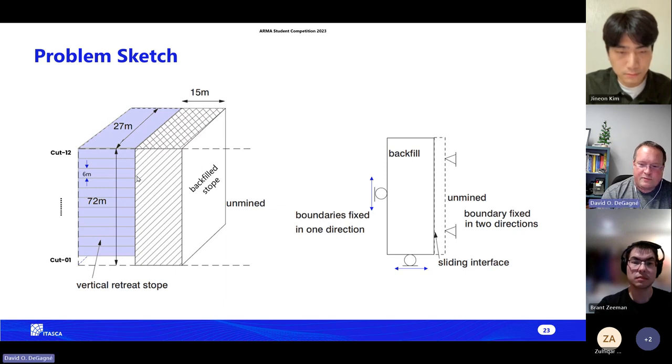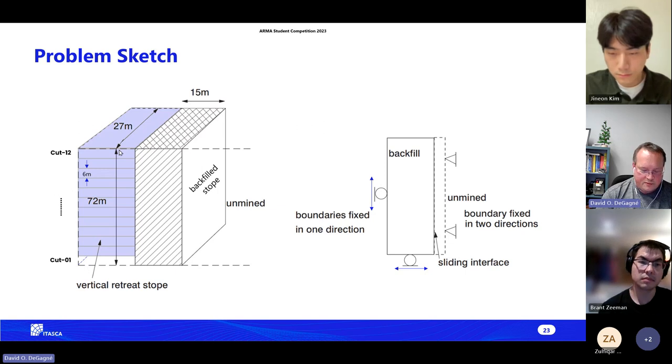This is a relatively large dimension. If we were just to remove everything instantaneously, there would be a sudden redistribution of forces, and the model could behave dynamically, and then we would get artificially induced damage. Maybe you can relate if you've worked with a testing frame for UCS tests. Those use a very controlled closure rate, depending on the material.